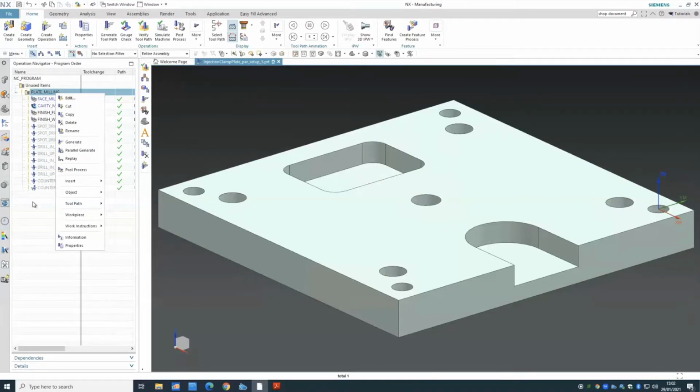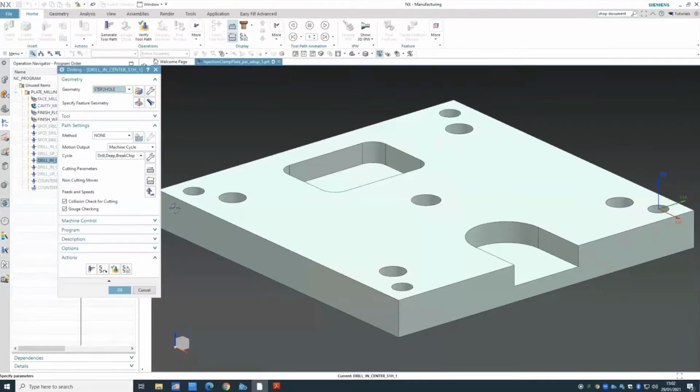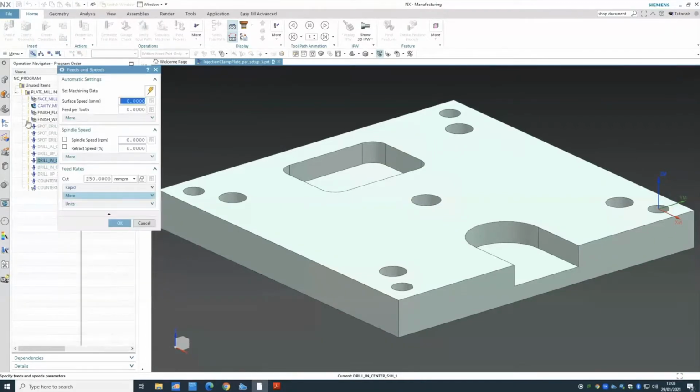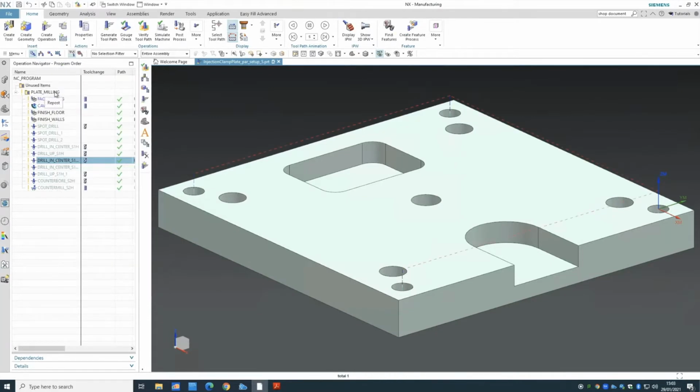Great. Make sure you've actually done everything. In your case for the assignment, you already have the feed and speed they gave to you. You just need to put them in here, and then once you put the numbers in, make sure you come back, click on generate and verify. Or just change the numbers, click OK, come back here, regenerate it and then re-verify it